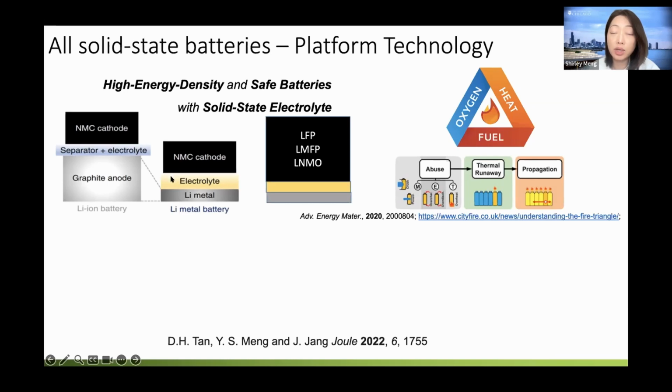It is important to realize there is a main architecture design change with solid state batteries. For instance, in the liquid, you usually have a polypropylene or polyethylene-based separator, but in the solid state, we directly use the electrolyte, making it a membrane as the separator. So there are no actual separators per se. Another important thing is that in solid state batteries, and I will show you later in my talk, there is a difference between so-called catholyte versus anolyte.